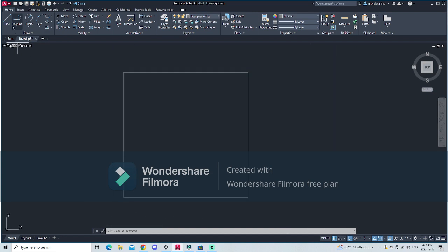And we're going to want to draw a desk for us to actually put an office chair at. So we're going to click the midpoint here, go down, say 0.5, enter, go to the right. Let's make the desk chair go here, or let's make it go 1.5 meters to the right. And then 1 meter up. Let's go 1 meter, or 0.5, just to round it out with the other side. Perfect. So here's our desk that we're going to make an office chair for.